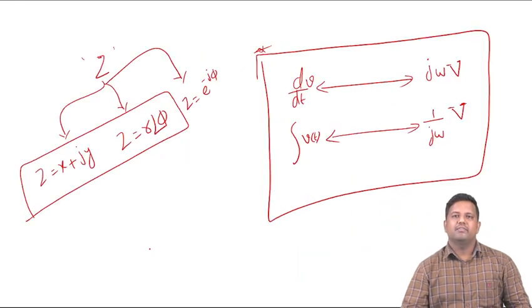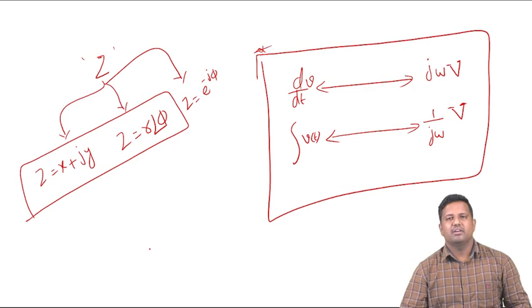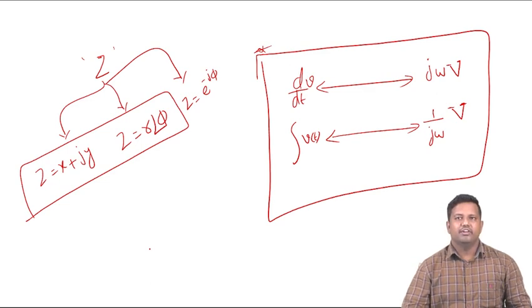Once we convert time domain signals into equivalent phasor domain signals, we can conveniently and very easily do all circuit analysis, like calculation of network total impedance, total admittance, total complex power consumption, total active power, reactive power, apparent power, and we can comfortably draw the equivalent power triangles of any circuit, or calculate the power factor of any particular portion, by understanding these fundamentals of AC circuit analysis.